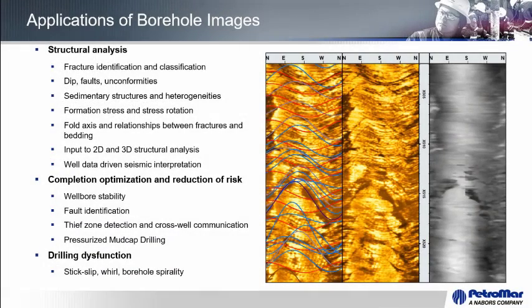Thanks, Tollef. When looking at the analysis of these images, there are a whole series of ways we can look at them. We can undertake the type of analysis that we could from any other borehole image. Basically, we can undertake structural analysis, look at fractures, and classify those fractures into different types, and that's what you're seeing in the image on the right, where we have different colors representing different fracture types, mostly the blues and the purples, plus our bedding, which is in red.